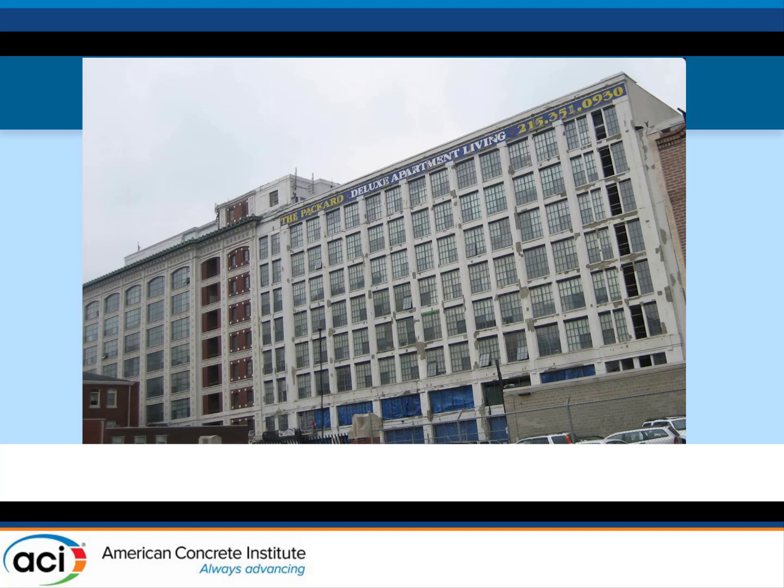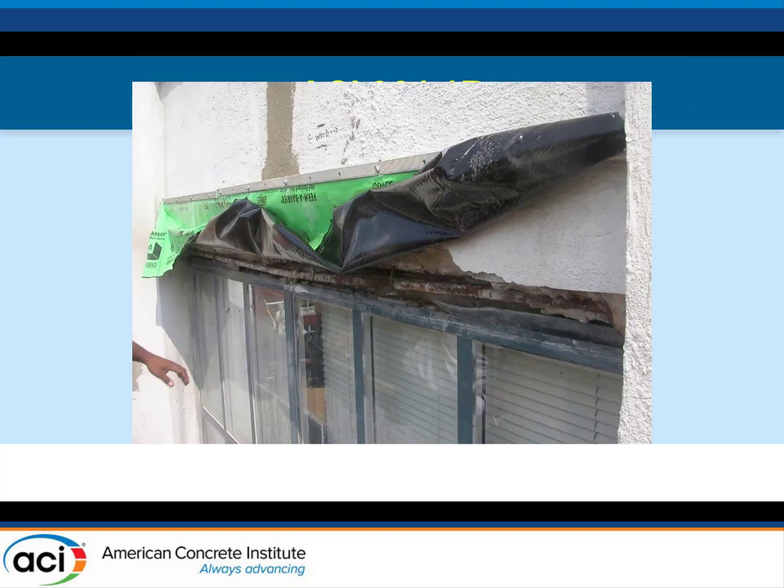So when we talk about expected service life of repairs, when we got into this, they had redone this building in the 80s. You had another 20, 25 years on it. And we're looking at it, and the owner's just like, well, I have all this concrete degradation again. So we got up and looked at it close. What's not apparent here is they never did any of the concrete repairs back then.